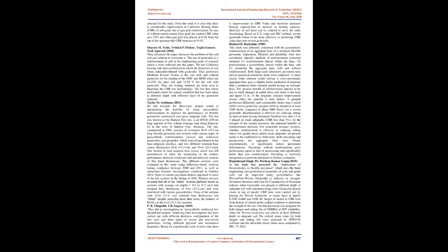One section in each nominal base course sector was left unreinforced to allow for monitoring of the relative performance between reinforced and unreinforced sections of like base thicknesses. The different sections were evaluated in this study using deflection-based, superficial testing conducted between 2008 and 2011, as well as subsurface forensic investigations conducted in October 2010.